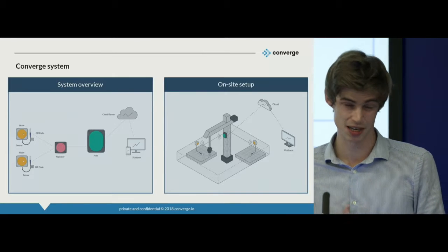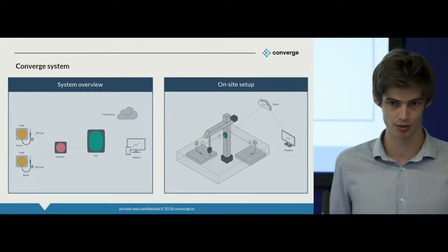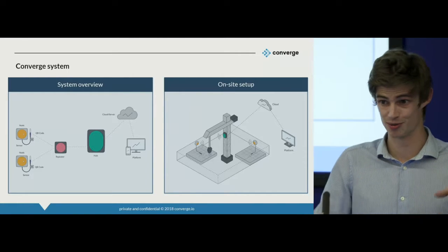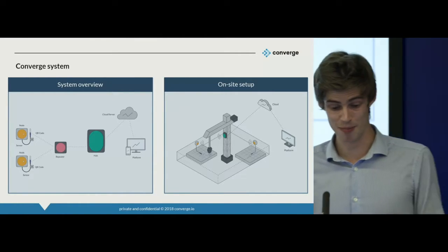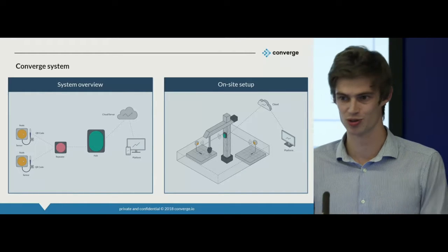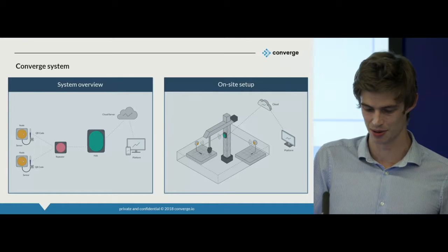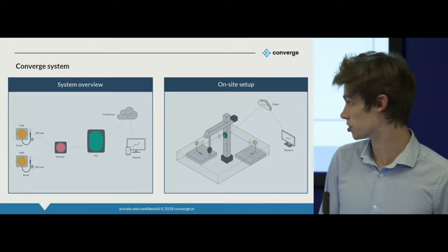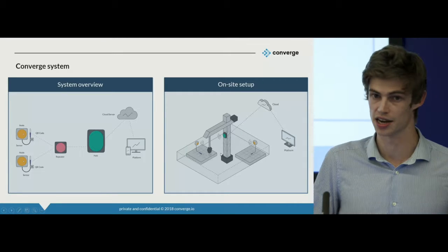So in terms of our setup in itself, we use what's known as a mesh network. So we install effectively a wireless network, quite similar to your home router setup, around the site in itself, and it has to be dynamic in case things move on construction sites. You get big sheets of steel getting put in the way. So the network itself is quite adaptive, and that allows us to monitor several locations at any given point in time.